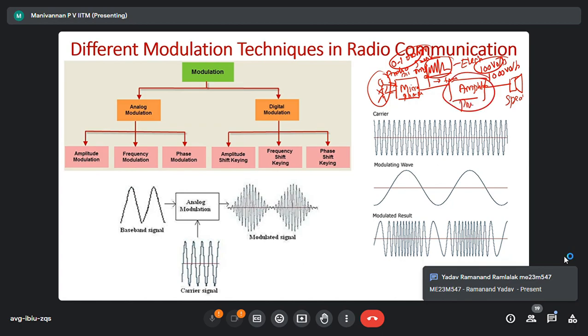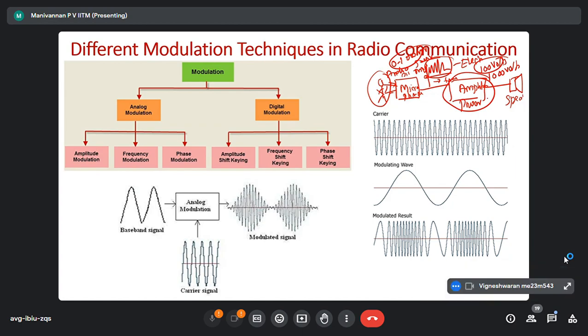Sometimes they call it a power amplifier. What happens? The millivolts are converted to volts, and also the microphone gives current in the order of milliamps or microamps. The microphone not only generates voltage, it generates current also. The current will be in microamps or milliamps. That is not sufficient to drive this speaker, correct? Speaker, what is the power?